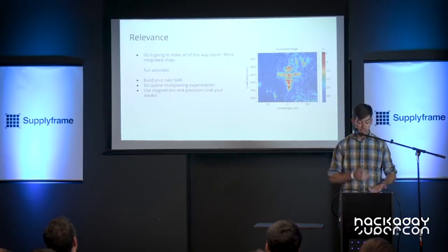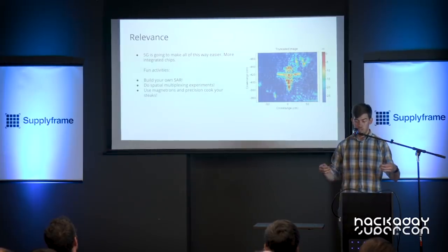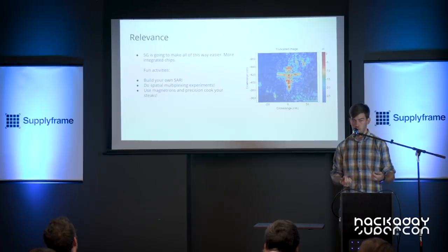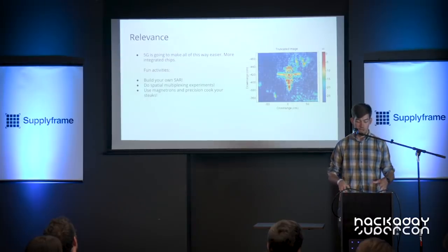And a lot of these chips actually have a lot of stuff built into them. It's really cool. All you have to do is literally connect the antennas to them. Most of them will do 4 ports at once from a single QFN part, so not even that crazy of a package. They have phase shifters already in them. They have amplifiers already in them. And of course, they're designed for data, so everything is supposed to be really linear and isolated inside of there, especially given the data rates they're trying to achieve with 5G stuff.